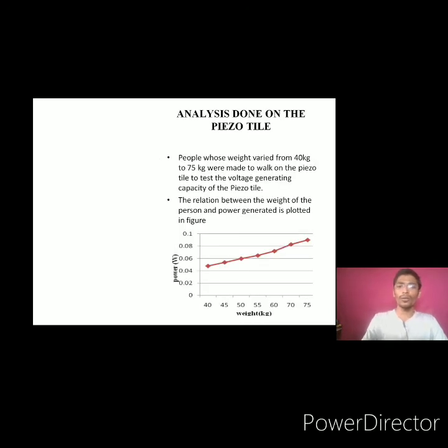As the weight varies, the power generation also varies. If a 40 kg person steps on the piezoelectric footstep, it will generate 0.05 watt. And if a person of 75 kg weight steps on this piezoelectric footstep, it will generate 0.09 watt of power. The power generation of a piezoelectric sensor is very low.